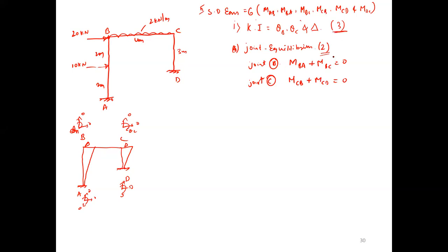One is remaining. Which one is remaining? Sway. Deflections. Sway. So that is your next step, the sway condition. See, here you are getting one equation, but you require 3 unknowns: theta B, theta C, delta.